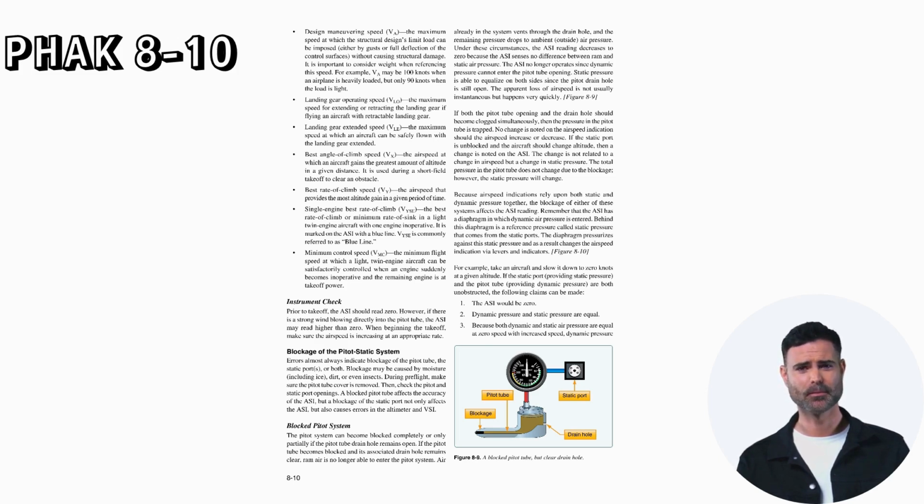Instrument check. Prior to takeoff, the ASI should read 0. However, if there is a strong wind blowing directly into the pitot tube, the ASI may read higher than 0. When beginning the takeoff, make sure the airspeed is increasing at an appropriate rate.